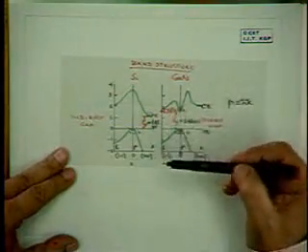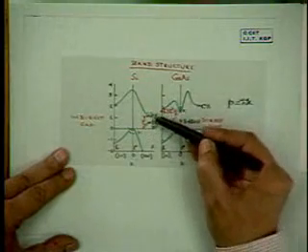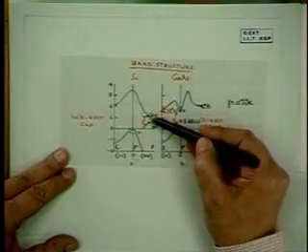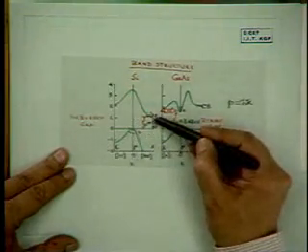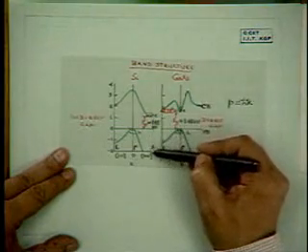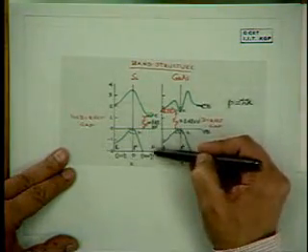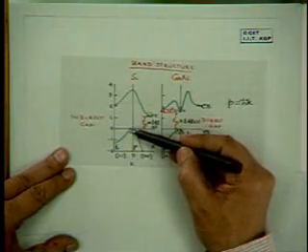One of the most important things to notice in these diagrams is that the conduction band minimum in silicon is displaced from the k equal to 0 point. So the conduction band minimum is displaced towards the 1, 0, 0 direction, whereas the valence band maximum is at k equal to 0.